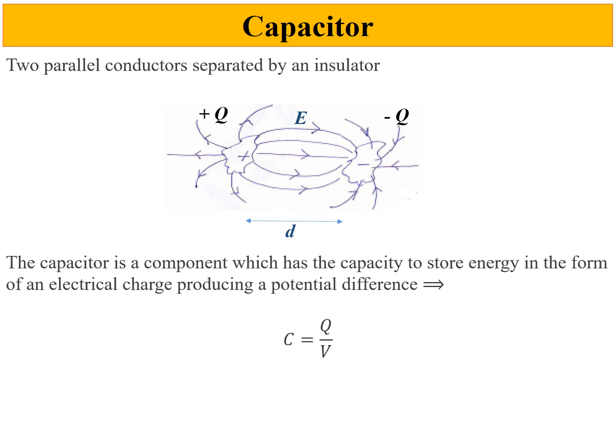For example, if I tell you we have a given capacitor that has a capacitance of 1 farad. By the way, the unit of capacitance, as you know, is the farad, because 1 coulomb over 1 volt is equivalent to what's called a farad, after Michael Faraday, who was the first to use this unit and to measure the capacitance of a given capacitor. If we have a capacitance of 1 farad, this means that if we have 1 volt here, the charge will be 1 coulomb. So 1 over 1 is 1 farad.